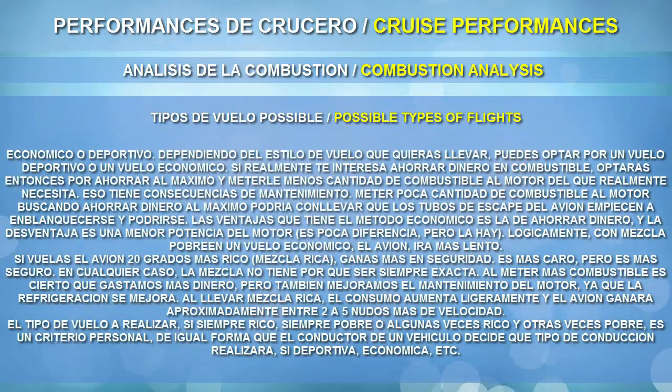Okay, so basically, if you fly rich, you won't get light speed. So if you were thinking of getting light speed and going to Mars in 1 second or immediately, I don't know what time, you won't do that. Okay, I won't do the calculations right now to fly at light speed to go to Mars. What I'm telling you is that you will get only 2 or 5 additional knots when flying rich. But the good thing about flying rich is that your flight will be safer. Okay, it's like sporty driving, let's say. And lean, you will save money, and perhaps you will have more range and nautical miles.